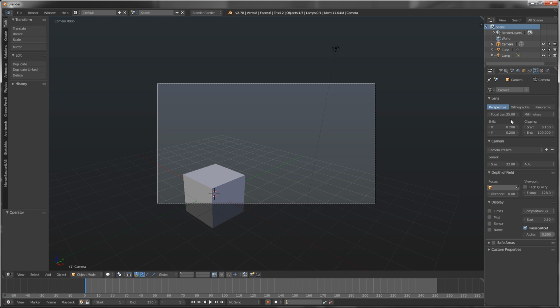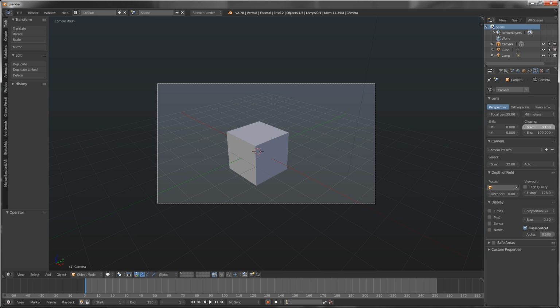Clipping is the interval in which objects are directly visible. This is a useful option when doing special effects within Blender. If we start at 10, for example, we notice a gray bar raise across the bottom of the camera view, and part of the cube is starting to disappear.